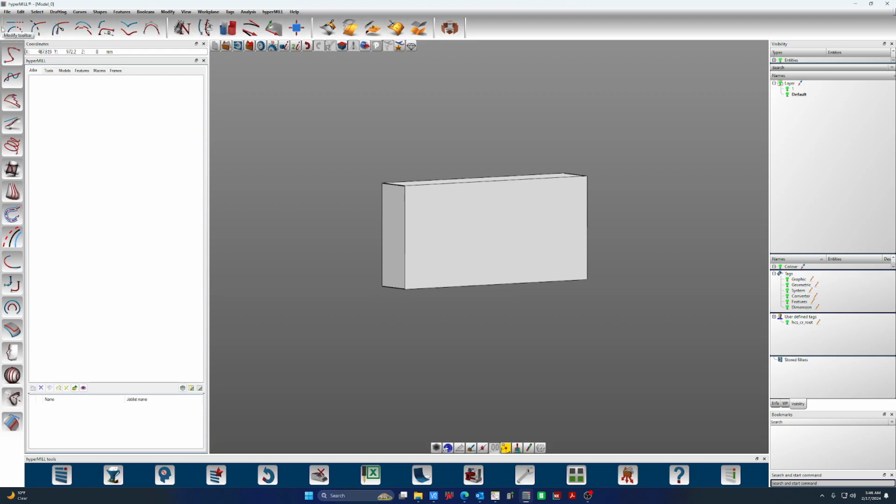Depending on the type of geometry you have, the dialog box is going to change a little bit. What I do find useful is automatic trim. I have two lines that intersect one another and extend beyond one another. This trim is just what it sounds like. If you have this highlighted, you go over to a curve, it will sort of highlight whatever side of the curve you're on and allow you to trim off that excess. Trim curve does something similar yet different. It's basically a non-automatic version of this, where you're selecting the curve and kind of selecting which side you want. Automatic kind of determines it depending.